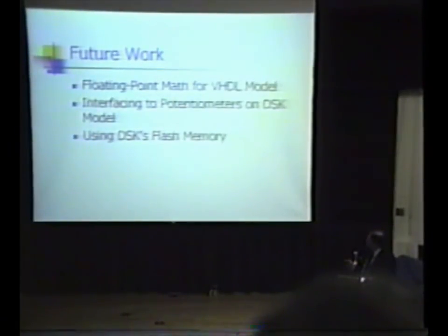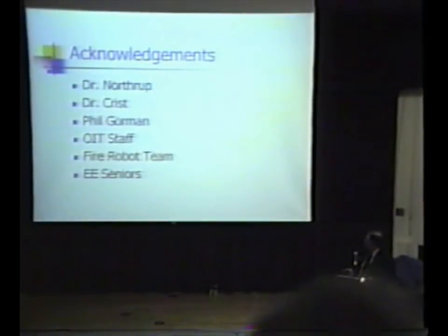Future work would be to implement floating point math for the VHDL model to get the bit precision to make the filters work, and interface to potentiometers on the DSK model and use the DSK's flash memory so it's not dependent on the computer.